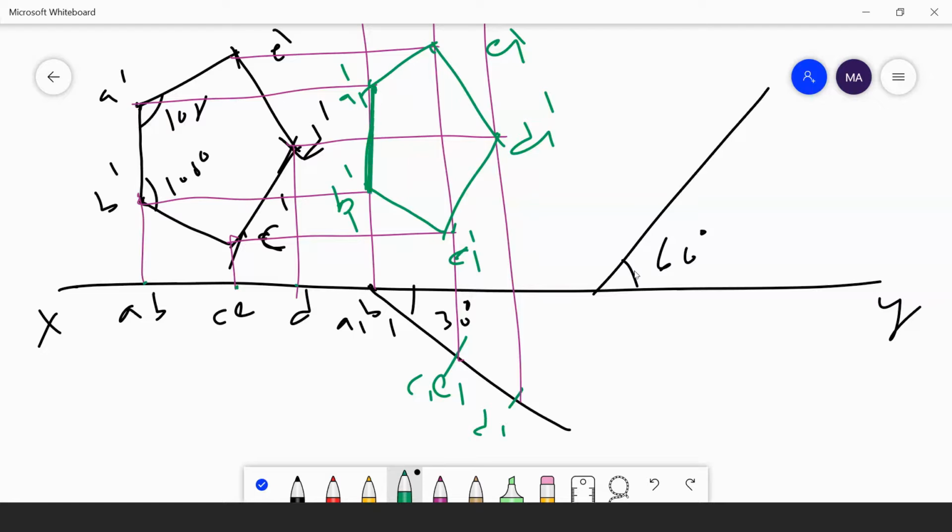is AB. So I am considering the point A here, point B here. This is B2 dash. Understand? I am measuring from B to A and cutting an arc here. Here I will get A2 dash. Understand? I am measuring from B to C using the compass. Take the compass, measure from B to C, cut an arc from B here. Similarly, measure from A to C. Take the compass, measure from A to C, cut an arc from A, you will get a point P2.